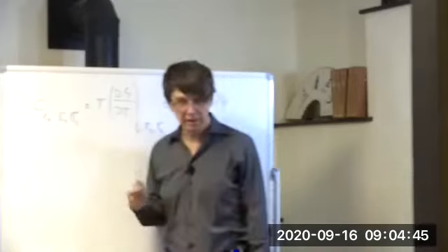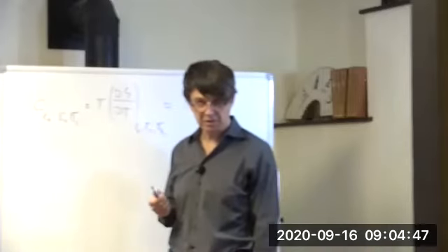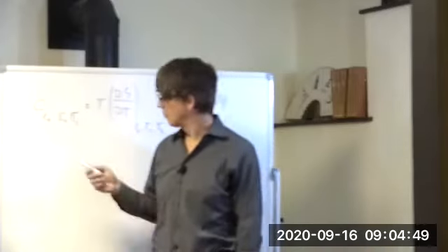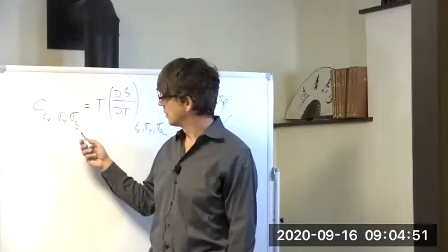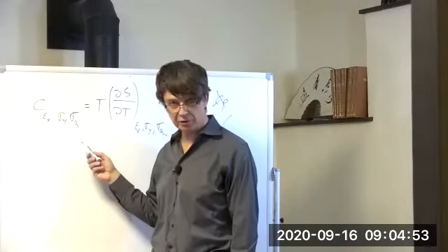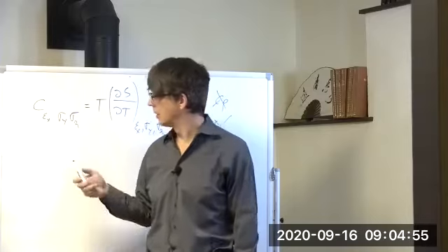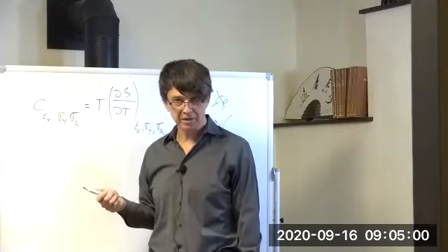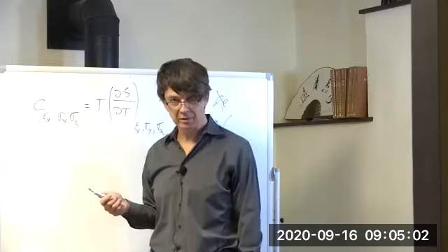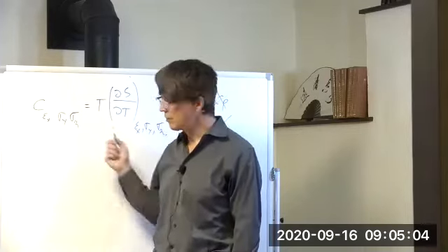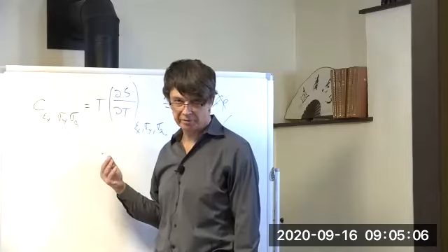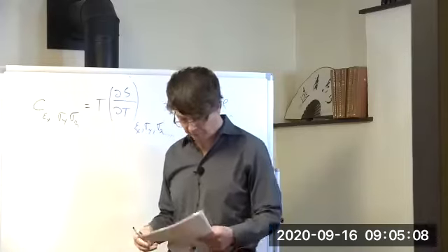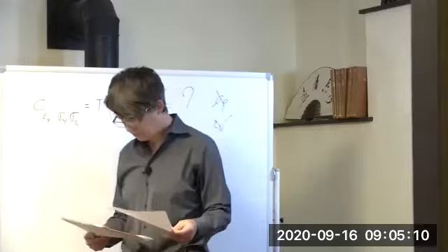Looks to me like it's going to be in between somewhere. Because I have two stresses constant, that makes it kind of close to Cp, but I have a strain that's constant, so that makes it closer to Cv. In Cv, I hold the three strains constant, because I hold the volume constant. In Cp, I hold the three stresses constant. So it's going to be somewhere in between.